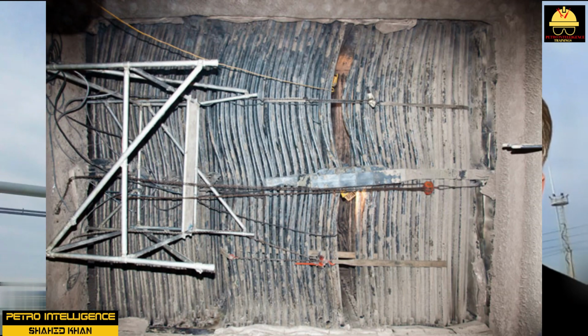Sagging or bulged tubes. As previously discussed, sagging tubes occur when guides or supports break. They also occur because of other factors such as when the inside or outside of a tube fouls and when there is flame impingement, reduced flow rate, or an overfiring furnace. Note that the diameter of a tube changes when it bulges.